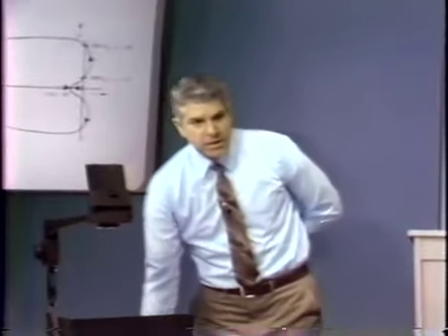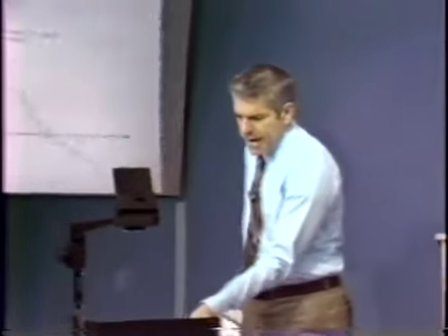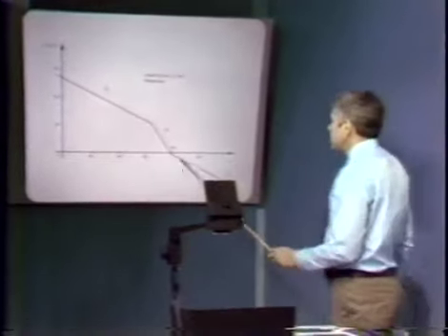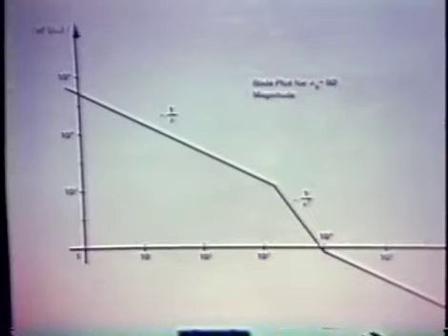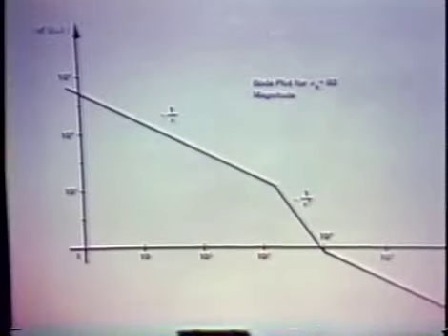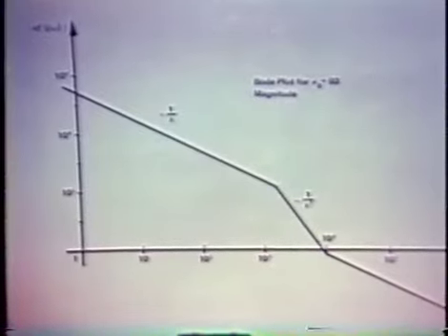We can again look at this in all the other ways we've seen. Here's the magnitude portion of a Bode plot. We find out that if we choose a value of A naught of 80, very nearly the maximum value we can get with our 100K potentiometer, and take care of the rounding in here, that crossover occurs at just about 10 to the 4th radians per second.